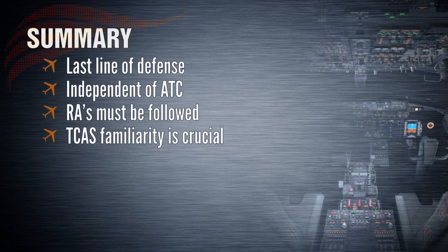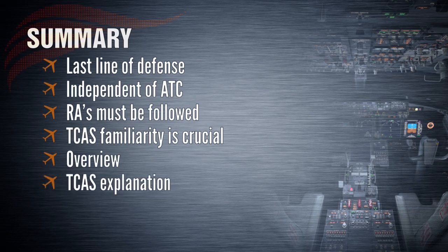In this lesson, we covered an overview of the background and objectives of TCAS, an explanation of how transponders and TCAS work, TCAS advisories and displays, and TCAS mode control.